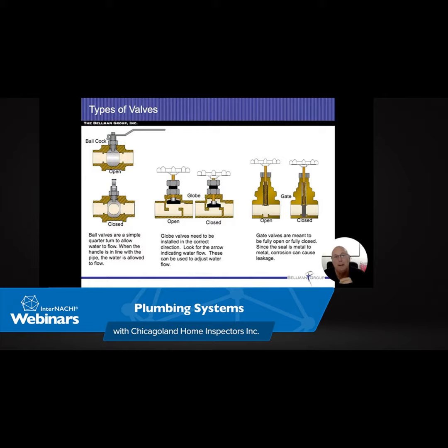We have a community up in Lake Forest that up until about the last 5 years ago, every waste line in that house had to be cast iron. Up to and including the trap for sinks, kitchen sinks, bathroom sinks, toilets, everything had to be cast iron inside that house. That was a waste line. Finally, it's gotten overturned, and now they're going to go ahead and let PVC come into play. I mean, as far as I'm concerned, PVC is terrific.